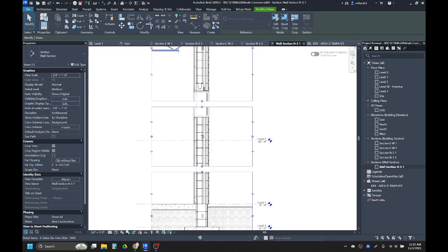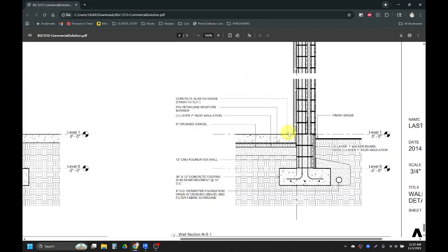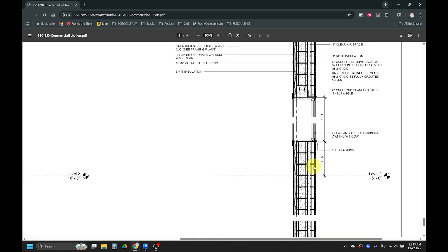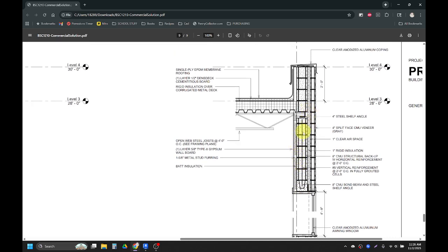Okay. The rest of the components, and I just want to double check again that I don't leave one out, but the rest of them, I don't know why that keeps coming in so small. Could be stuff we bring in. So these little dots here are rebar. We could put those in as detail components, or we could just draw them in manually. And I'm just going to draw them in manually. The same thing for what's going on in my bond beam here. So the rest of them are all just going to be detail components that I actually just use detail line